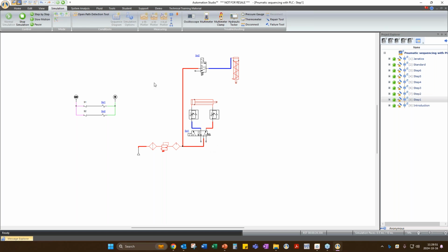Okay, so I have to perform the operations on this circuit. Solenoid is connected to this, and the solenoid connects to this DCB. So by connecting this, I will simply click on the switch S1. You will find this solenoid is getting actuated, and it allows the flow from here to here through this orifice. Okay, it is getting extended.